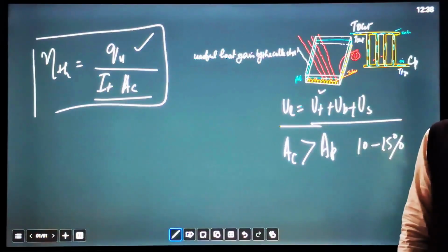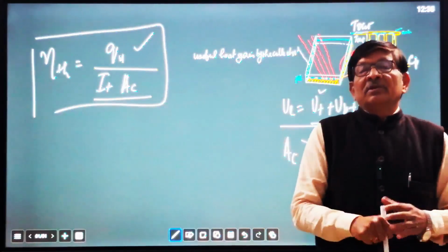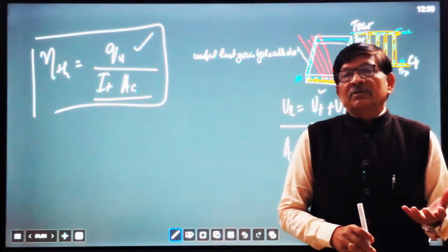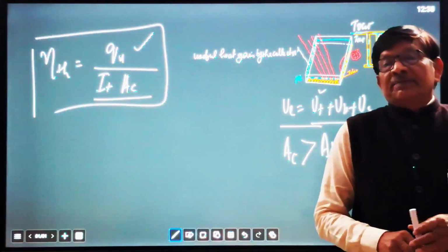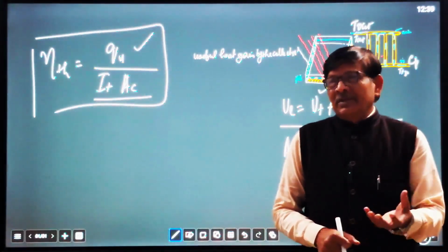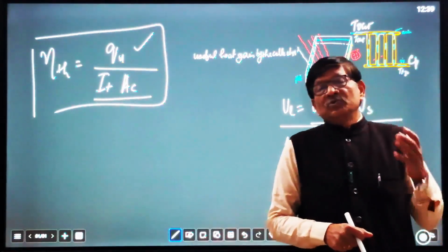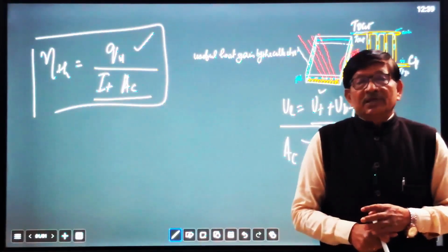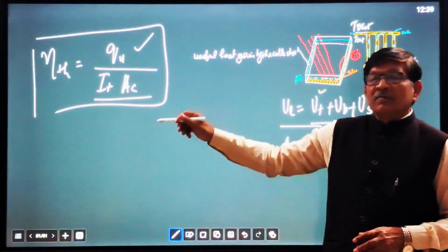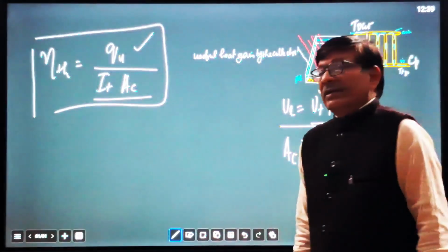the stagnation temperature, because whenever we design a collector, stagnation temperature means the temperature when the flow stops. Suppose flow is stopped and radiation is continuously coming. What will be the maximum temperature of the collector absorber plate? That is very important, because if the temperature goes very high, the insulation material inside must be able to bear it, and the absorber plate may even melt. What kind of material do we have to use in the insulation and absorber plate so that it will bear the high heating due to stoppage of flow of the working fluid? So that is a very important factor in deciding the collector stagnation temperature.